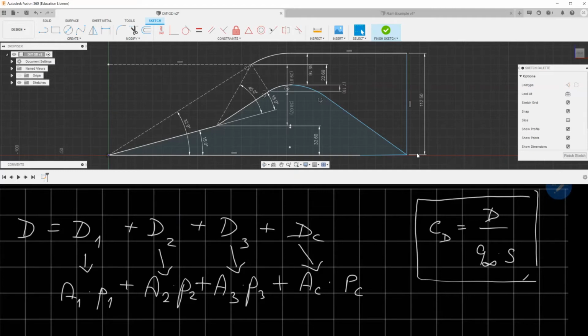quite accurate, because only pressure forces we have and viscous forces we neglect. They are 10, 100 times smaller than the pressure forces, so precision of our method is quite good. When I say good, you know, in gas dynamics, I mean the error is in order of 5%, precision 95% or less.